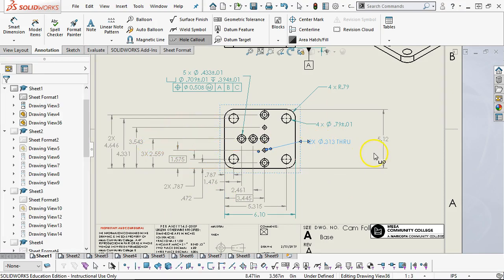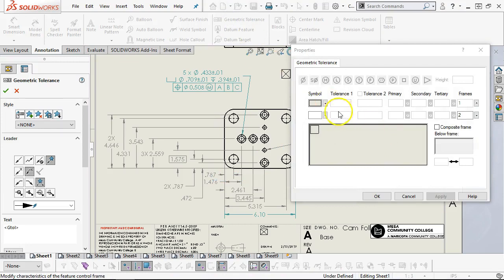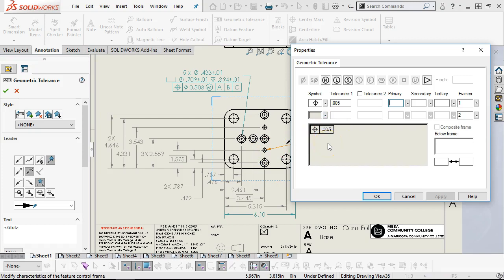Let's see, I guess we did the 0.313. With that selected, this is where you would go into the tolerance, and we pick up the positional. Let's stay with the 5 thousandths initially. We need to think about what it can grow, because this is that pin and bore condition, where our press tolerance is going to determine whether it's a transitional or interference fit.